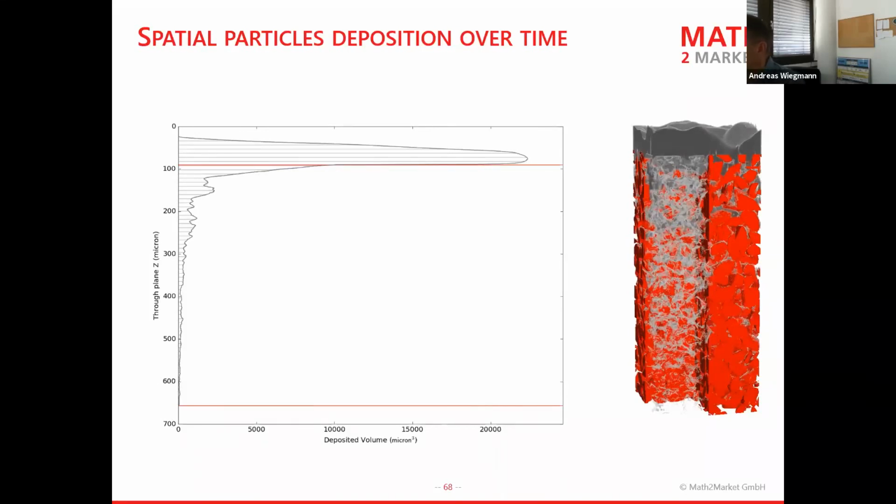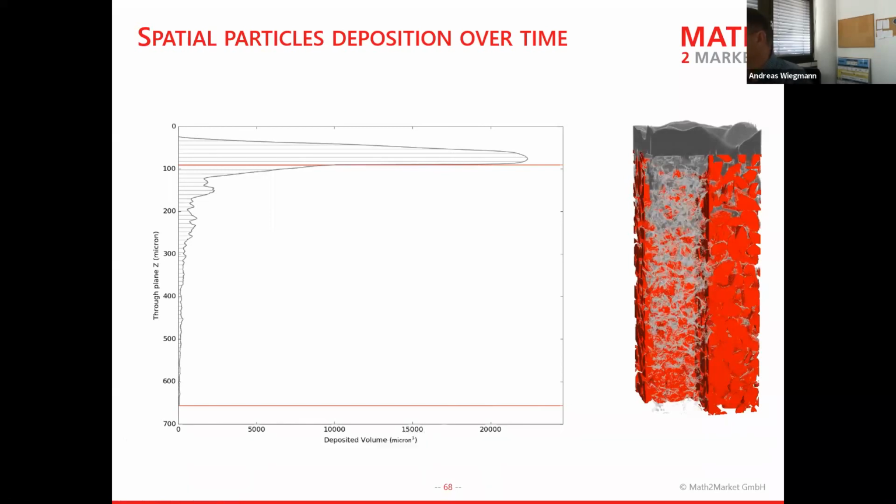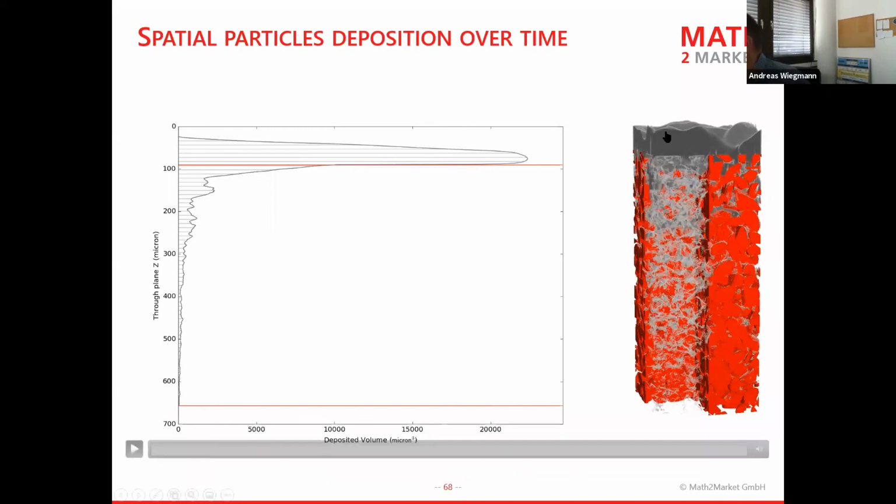We do this by, this was about 150 or so flow simulations. We simulate the flow, we track a bunch of the soot, and then the flow field changes. So the soot actually becomes a porous media here. Up here, it's very obvious. This is not resolved by the grid anymore and gets what's called a flow resistivity that has to be modeled.